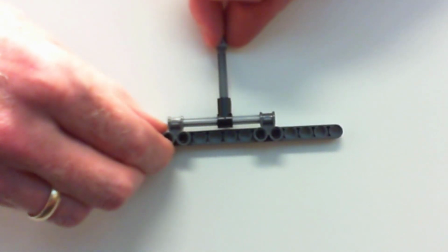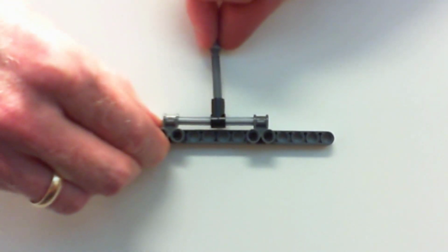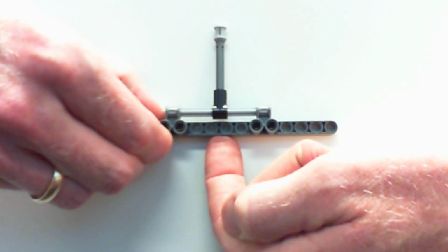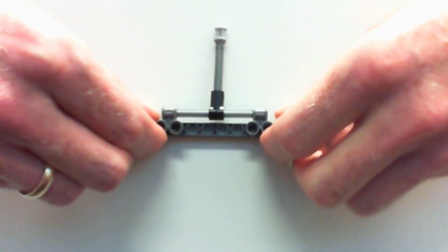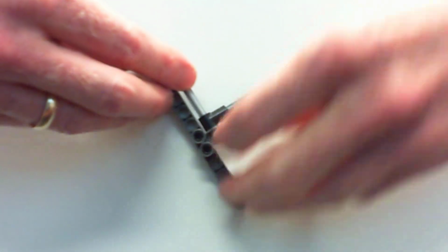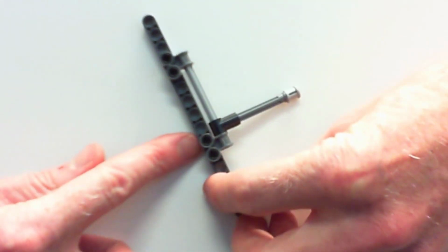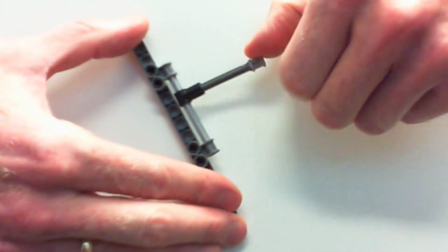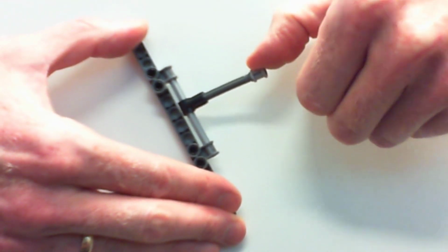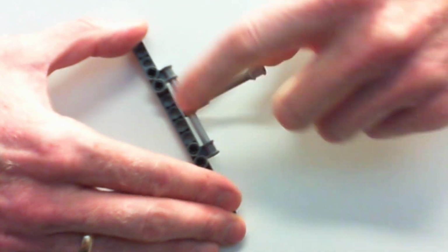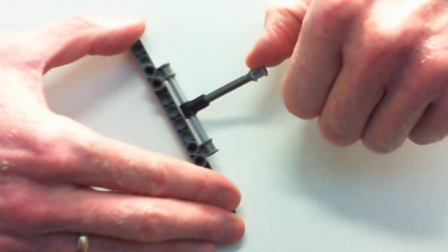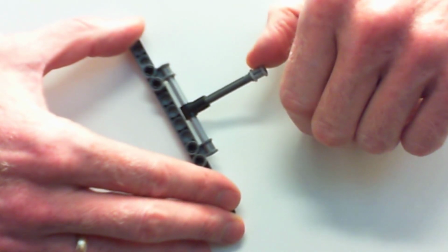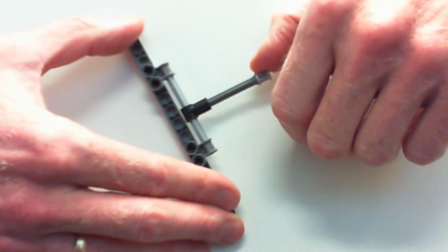Okay, and so we call this a fixed collar on a smooth rod. It comes out with two different reactions. One of those reactions is always going to be perpendicular to the rod. So if the rod is horizontal, the force is vertical. If I put the rod here at an angle, that force is always going to be perpendicular to this rod. And then an unknown support couple, that's this resistance to rotation, right? I'm bending this member here because of my resistance to rotation coming from this collar. Okay, so two unknowns, a normal force, and a couple which resists the rotation.